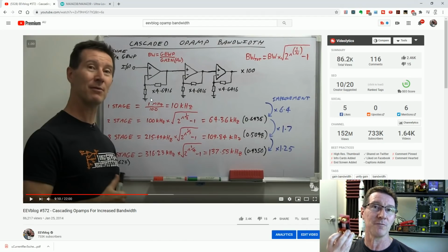Of course, it's designed for measuring small voltage drops across a sense resistor and overcoming burden voltage on a multimeter. But most people these days use it for low current measurement. That was never the original intended purpose, really. I just included the nanoamp range because I could.